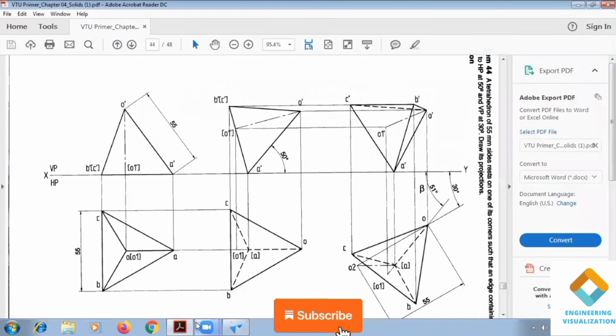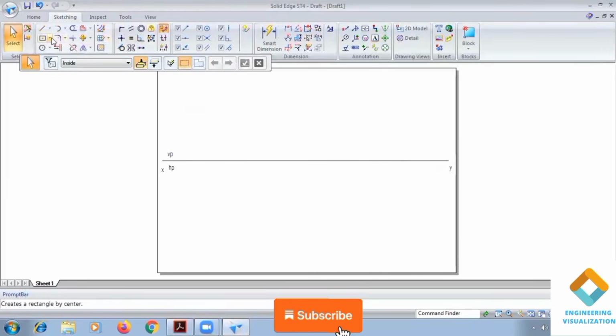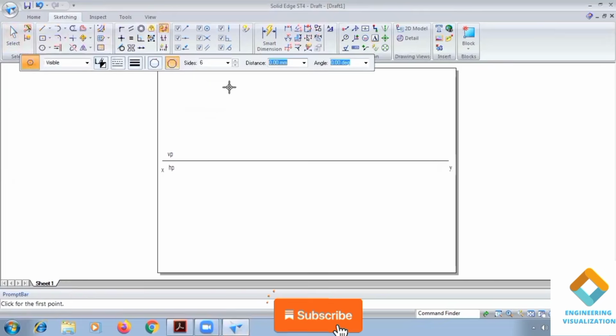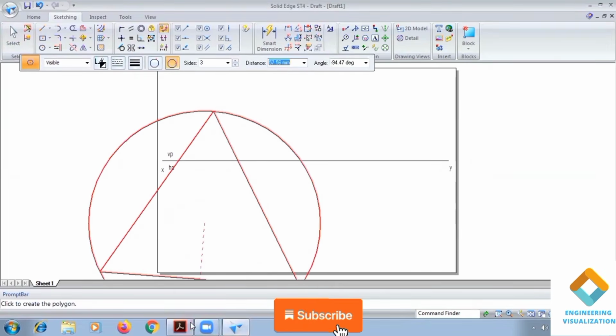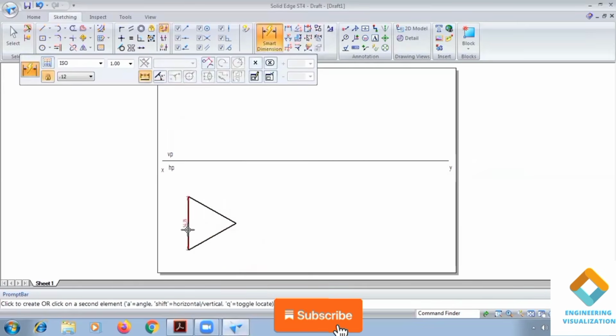We need to construct this triangular face. Go to polygon by center, make sure the geometric relationship is on, select three sides, thickness 0.50 mm. With respect to the edge we need to place it. The same problem has been asked in model question paper 2. Give the length 55, enter, and it will change.